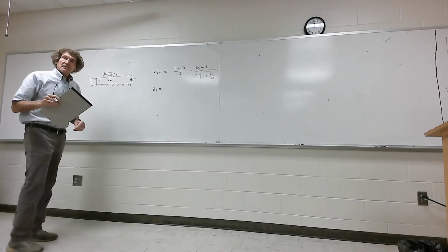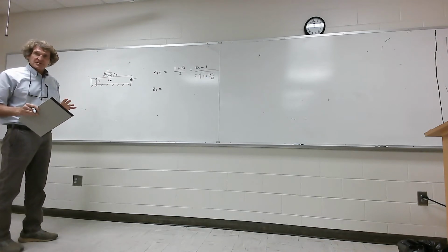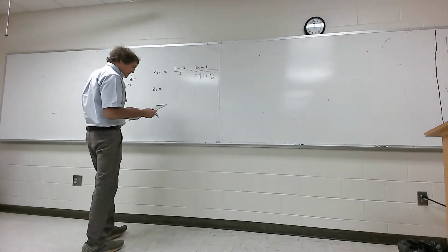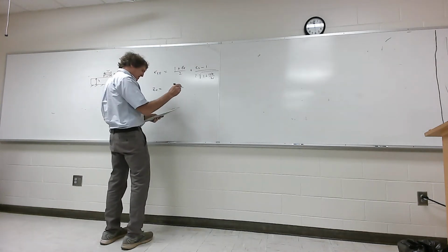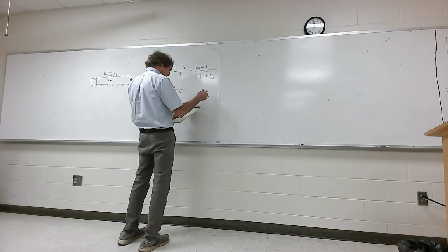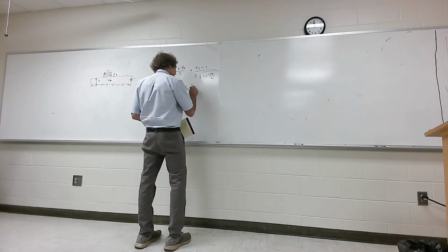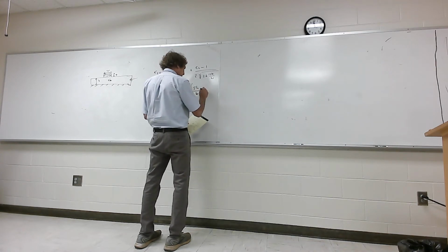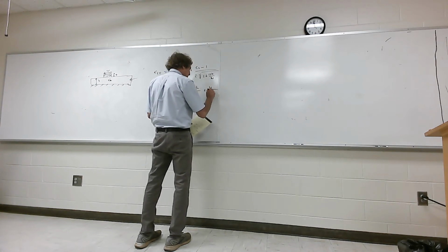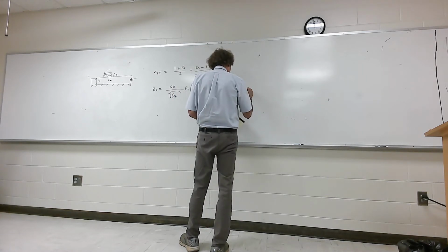So what we're really talking about is creating transmission lines on these boards. That's really it. They're not waveguides, they're transmission lines. And when you talk about this characteristic impedance, the first one uses 60 over the square root of epsilon effective. There are a variety of these. I know because I did a paper on this years ago, and I realized just how many approximate formulas industry has for this stuff. This is in ohms, and this is for W over H less than 1.